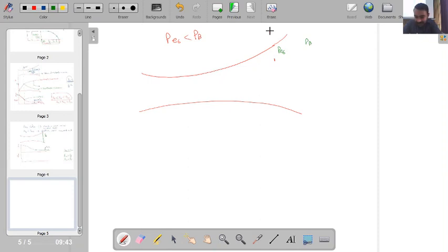I will be finding that at the corner of the nozzle there will be formation of an oblique shock wave, and this oblique shock wave will try to create this small pressure recovery over here. Okay, so this oblique shock wave will lead to pressure recovery, and here I will be having flow streamline, something like this.